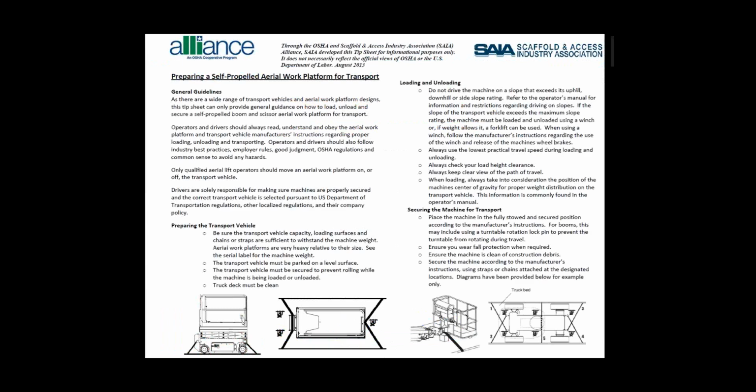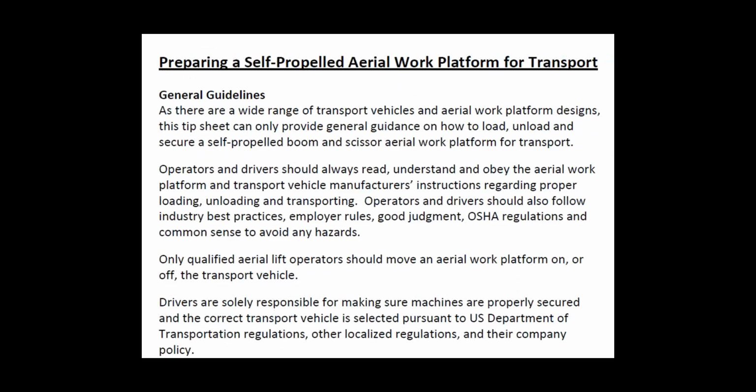The first thing we need to do, and this is the first tip sheet that the SAIA and the OSHA Alliance produced, I'm sorry, not the first one, but the first one that I'm going to use in this order, is preparing a self-propelled aerial work platform for transport, because we're not only operating the aerial platform, but we're also driving on regulated roads for the Department of Regulation. The first item on the tip sheet says that there's a wide range of trucks and aerial work platforms, so we need to take into consideration the operator's manual for the truck that we're using and the operator's manual for the aerial platform that we're operating.